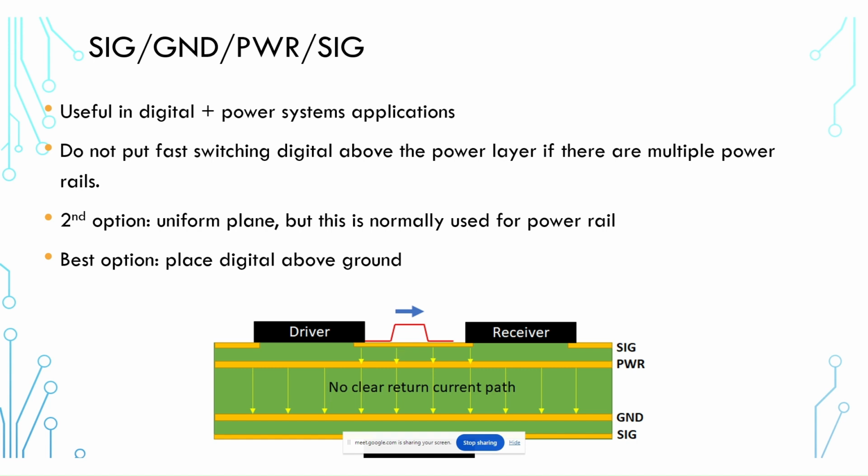So with lower frequencies, we may need to use some tricks in this stack up, for example, applying copper pour. Now here's an instance where the copper pour actually becomes useful, because that copper pour up on this top layer can provide a better return current coupling into ground, and then you would use your stitching vias to get back to the ground in layer 3. So this is just one of the instances where we can get some usefulness out of copper pour. It's not one of those things where we absolutely have to use it in every design, but it's helpful here in this situation where we do have to have signals on this back layer, but we don't have a clear return current path. And we'll show some examples of that later in the presentation.